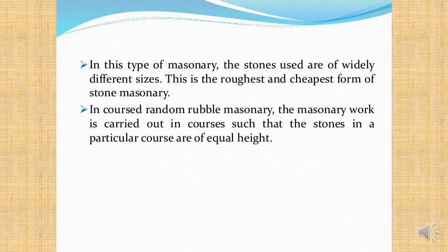And the masonry work that goes into making a rubble masonry wall is quite laborious because all of the blocks are random, and so when you are arranging a course, a horizontal length of masonry blocks, that's going to be wavy and jagged. And then you place a layer of mortar on top of that, and then you place another course, which again will be kind of jagged.